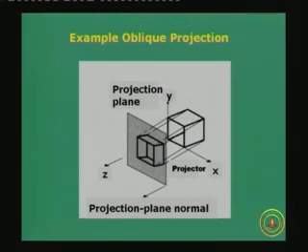So, how do you visualize this? Let us look at this figure. I hope you will be able to understand it, where the projection plane is the gray rectangle, and we are again taking the projection of a cube. It is a hollow cube again. It is easy to visualize if you take a hollow cube, because you can see the inside lines as well. The projection plane normal is the z axis. The projection plane normal, given at the bottom of the screen as the vector here, is aligned with or parallel to the z axis, and the projection plane is nothing but the xy plane, correct.